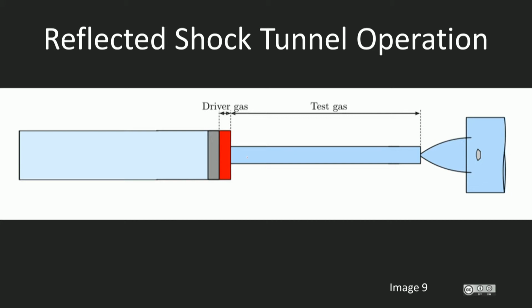However, eventually the pressure ahead of the piston rises to much higher levels than the pressure pushing it. Towards the end of the stroke, the pressure ahead of the piston rapidly ramps up, and the piston piles all of its kinetic energy into the driver gas. This process is called free piston compression.